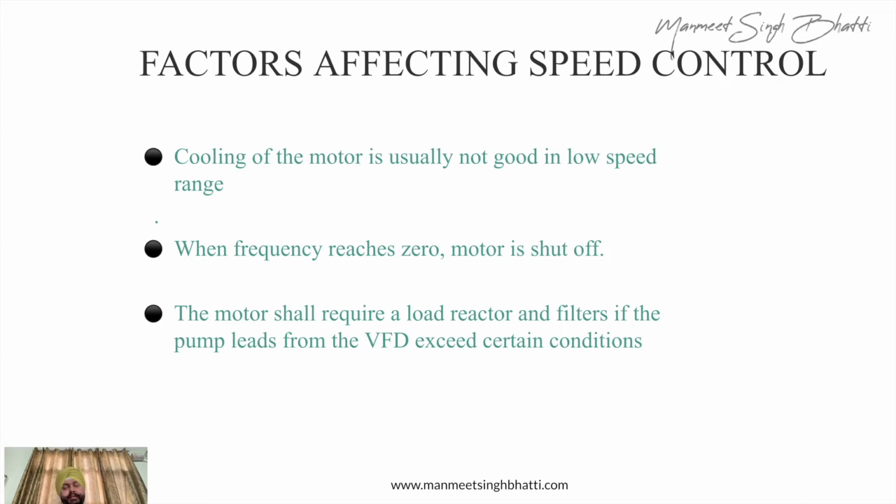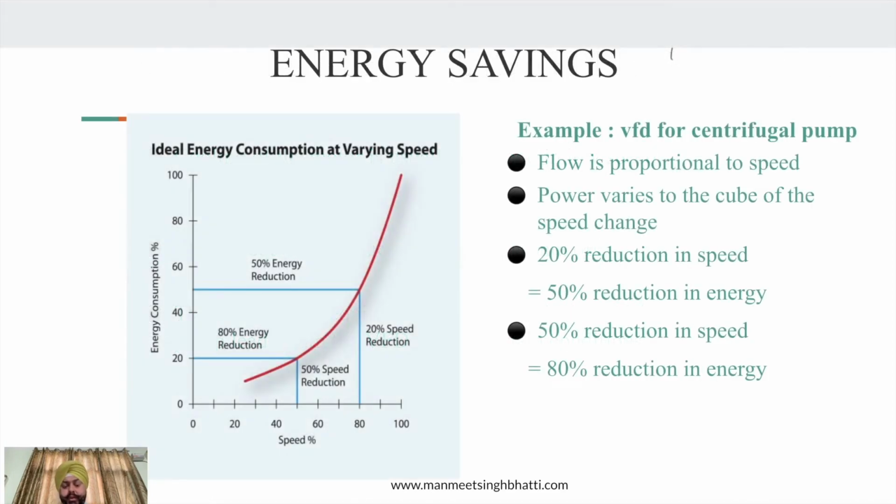Then the motor may also need load reactance and filters sometimes. This is basically because of the VFD output. The VFD output is a switching output. If the distance is very short, the switching output is not going to make a difference on the motor. But if that switching output goes over a longer distance, you actually get a backlash also. Once the backlash comes, you have a very big challenge. The backlash is not affecting the motor, but it is affecting the drive circuit itself, because it is exactly the opposite of what is being generated by the drive.